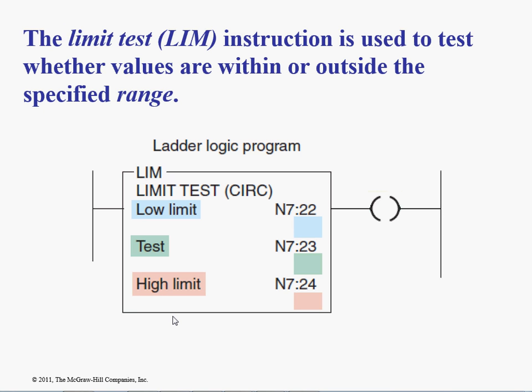Limit. Now, what did I tell you yesterday about your stoplight? How many people got all the way through and did both stoplights on your trainers? I did one side. Just did one side? How many timers did you use? 3? You did both sides? Probably you might use 6, or you could use some complicated and or normally closed, normally open logic, comparing the other lights to make sure they come on in the proper sequence.